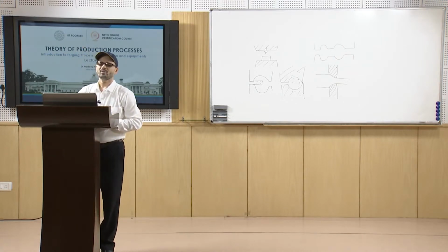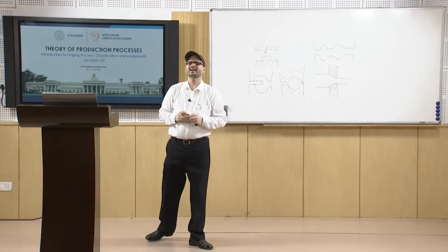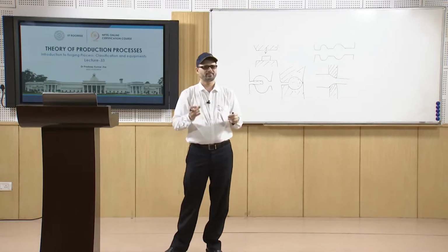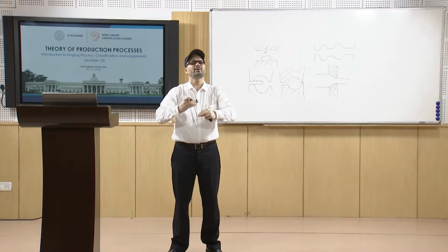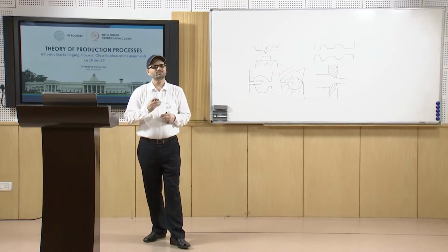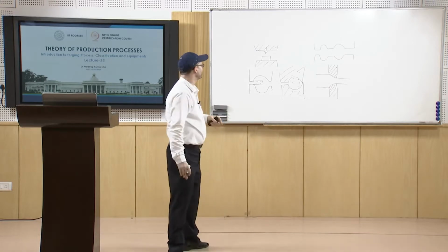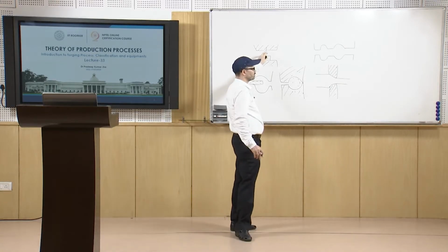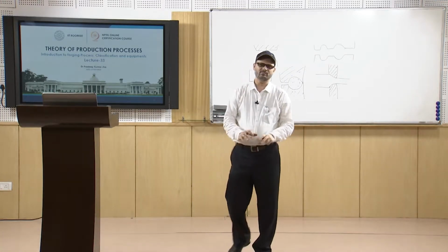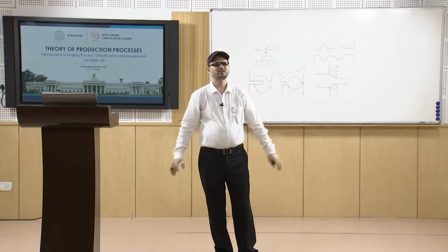Now, coming to closed die forging, forging work is never completed in one step. You have to go step by step. You cannot assume that once you have gone for forging, in one step itself you are going to get the final shape. In open die forging, as we have discussed, the metal will flatten over the surface kept at the bottom die, and when you apply the force, the metal will spread over it.